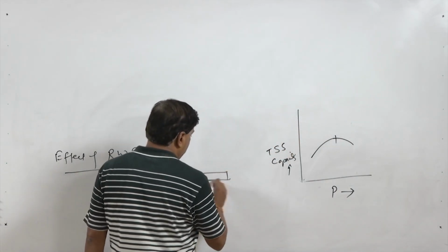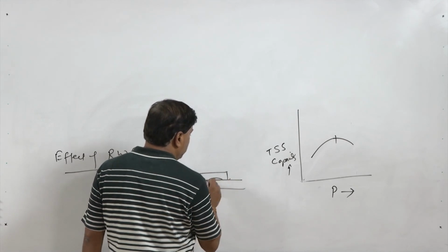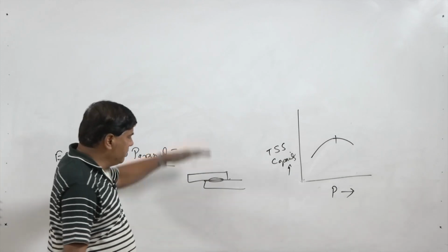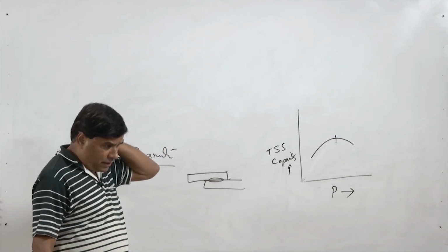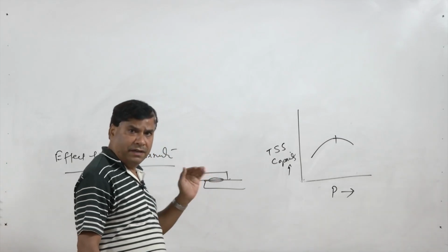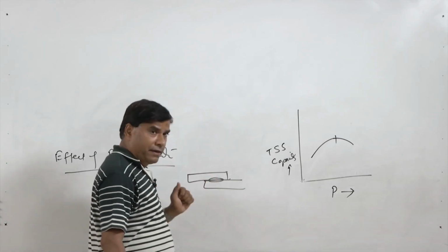If the pressure is too high, then increased metallic intimacy at the faying surfaces will decrease the contact resistance. So under identical current conditions, the amount of heat being generated will get reduced, and that in turn will reduce the nugget diameter.